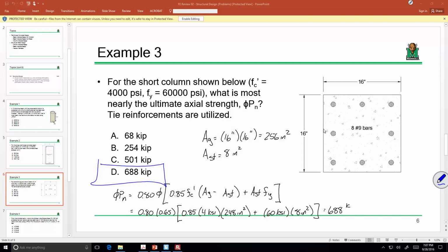When you coat rebar in epoxy, you make it slicker. So if you epoxy coat rebar, you require a longer development length. Does that make sense? Okay, that's the background. And those are the types of questions that are going to be the case.